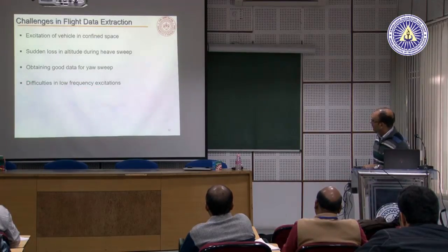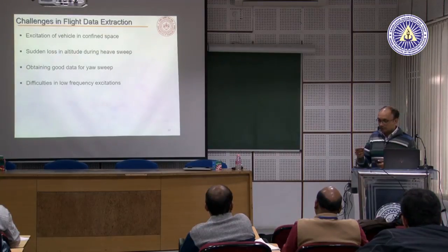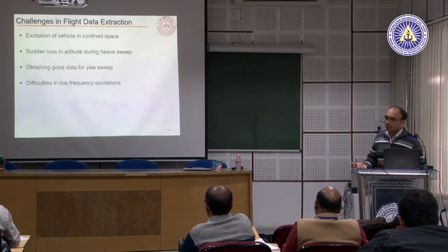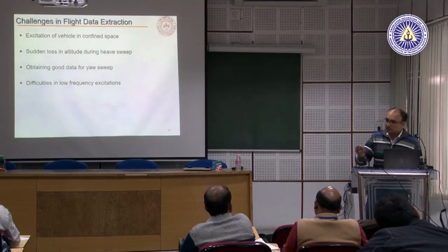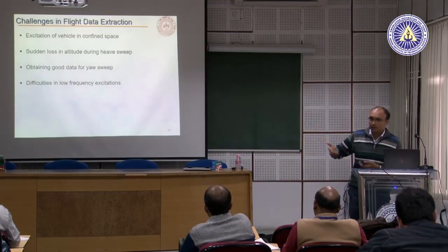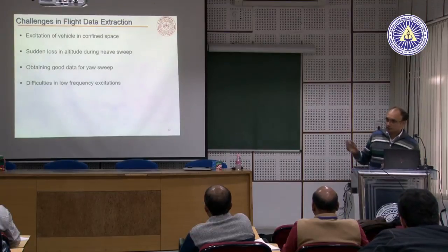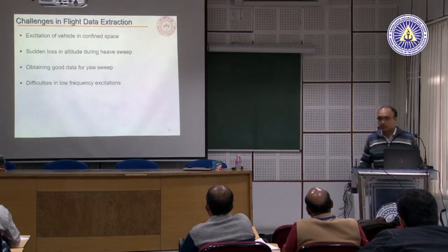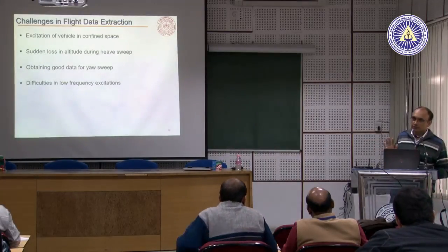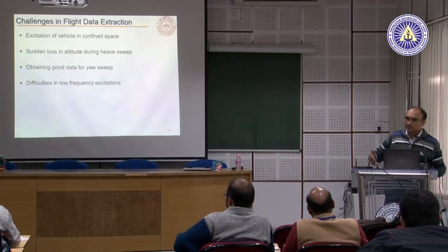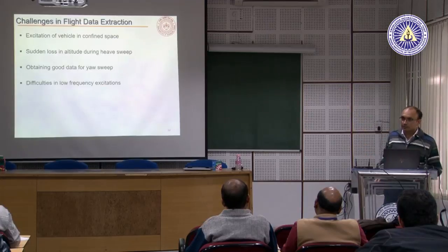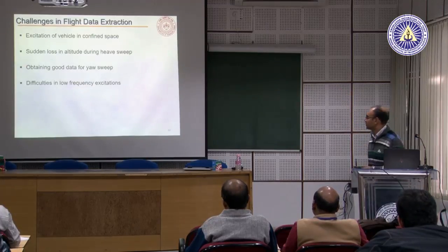It is also difficult to give low frequency excitation, because low frequency means you are giving a slow input, so the helicopter has more time to react to that slow input. So I am giving a change in theta 1s. By the time I bring it back, my helicopter will start moving forward. It will acquire some forward speed already. So another challenge is giving this low frequency input. High frequency is fine, I can keep oscillating very fast and the helicopter will more or less maintain the same position. But with low frequency, the confined space comes into the picture, because then it will go outside the range of the camera, or it will hit the wall. So those challenges are there.